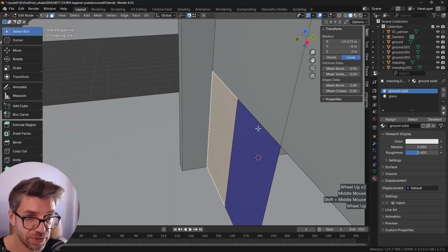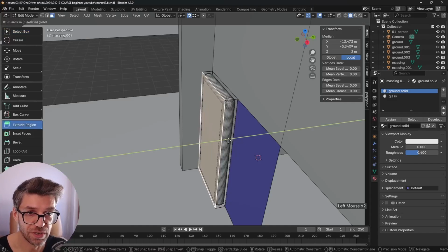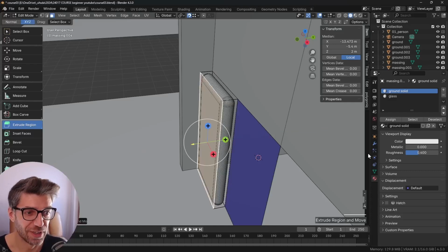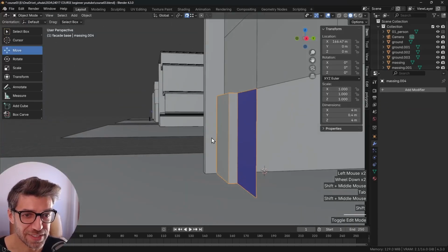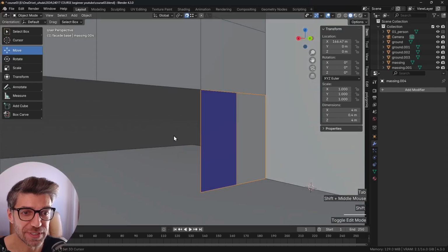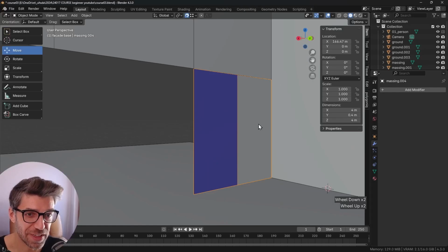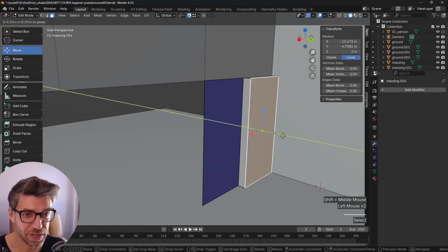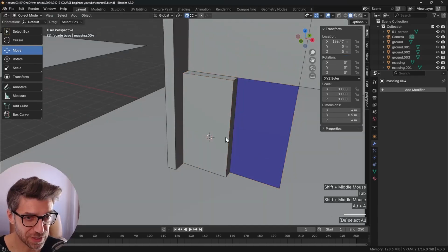Now, because they're separate but part of the same object, a nice thing that we can do is extrude just this region. And we have a bevel, that's why it's looking like a pill. Let's see, we're going to extrude minus 0.4. And now let's go to modifiers and remove this bevel because we don't need it anymore. Great, so that's it. Why do we separate the object? Because if we didn't have it separated and we were still sharing those vertices, we wouldn't get this rear solid face over here. In fact, let's move that rear face a bit as well. So let's go to move and move it 0.1, so 10 mil inside. Great, so that's just something that looks quite solid.